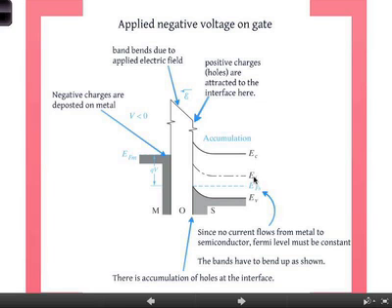The difference between them is the applied voltage. We know that. So far, so good. If the Fermi levels split, that means that the bands have to bend. Some of the potential falls across the oxide, so you get a band bending of the oxide. You get some field across the oxide, which is just like a parallel plate capacitor.